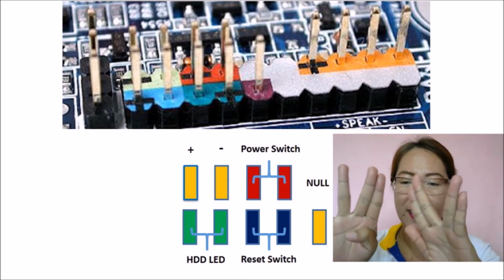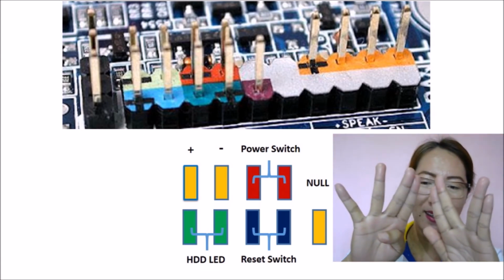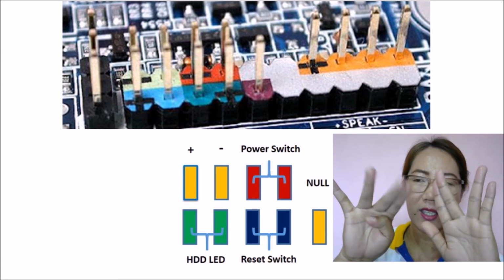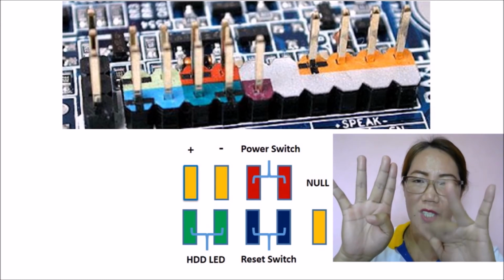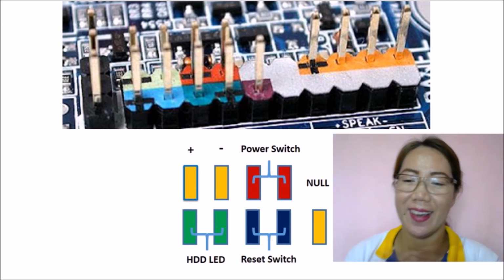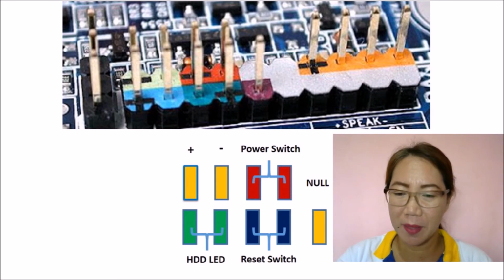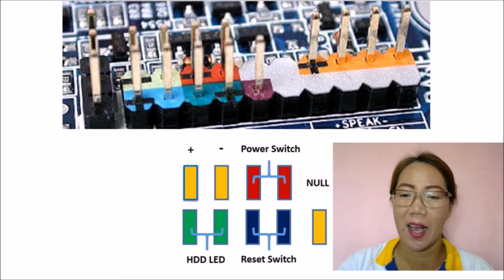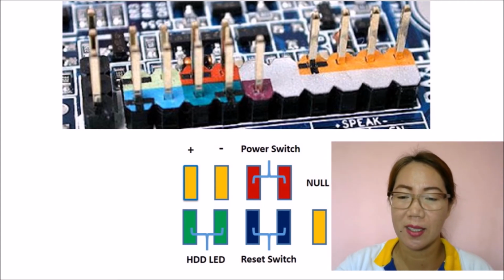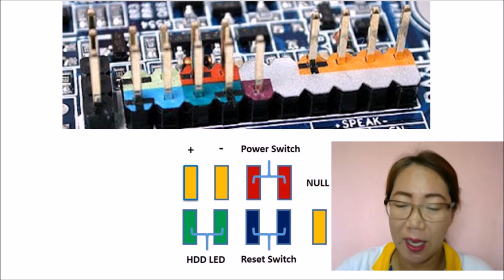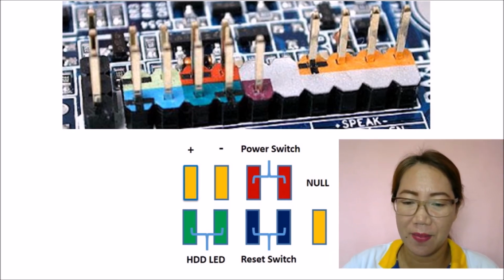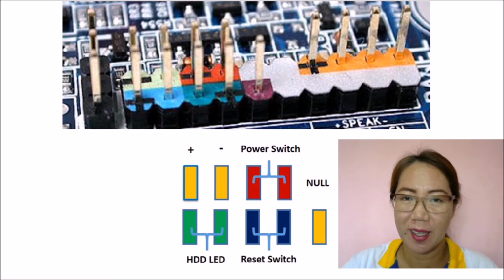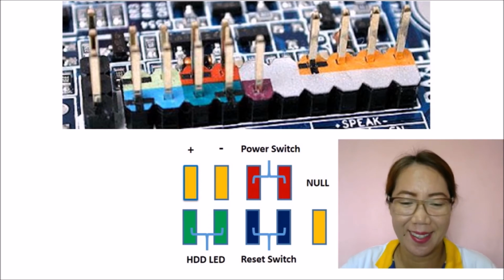Okay, FPC. Look at my hands. Power switch, negative, positive. Reset switch, HDD LED. You can memorize that one because it would be a great help if you will be servicing outside and you want to configure the front panel connection. I hope you enjoyed my little hand exercise.